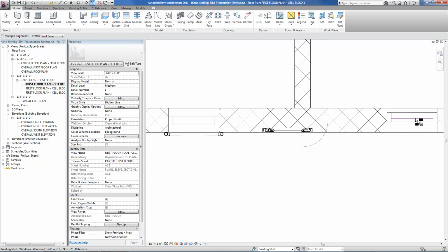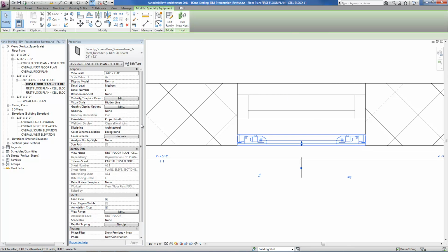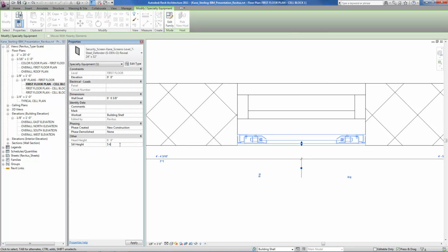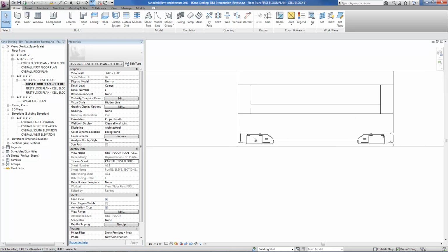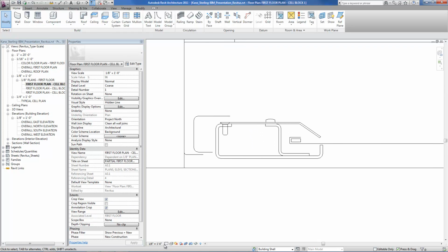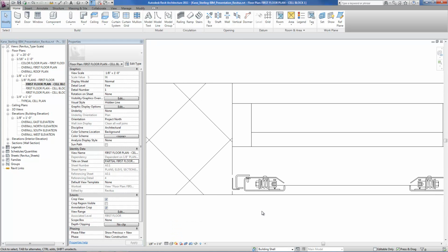Okay, back to the point of detail level. On any typical project, an architect will create multiple views of varying scales. High-quality Revit content takes these considerations into account by strategically planning and utilizing visibility settings. Simply put, less detail shows up in smaller scale views and more detail shows up in larger scale views. The primary reason for this process is to ensure that these families remain legible and graphically acceptable on all printed output throughout the bid document sets.